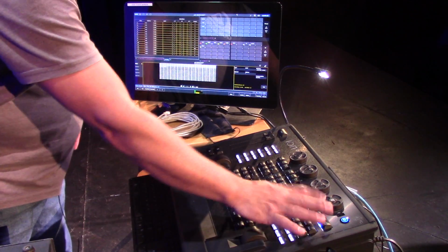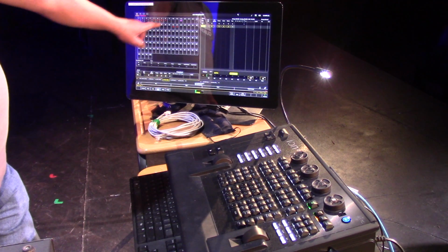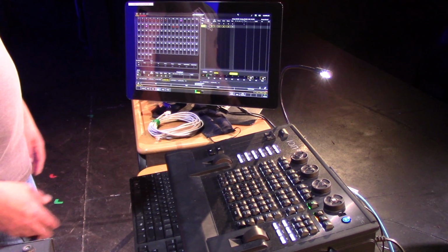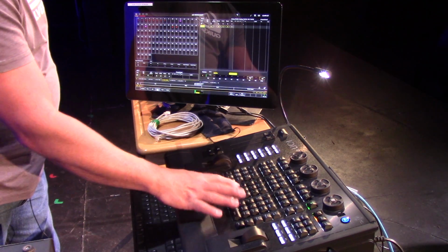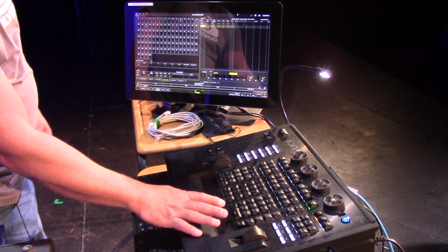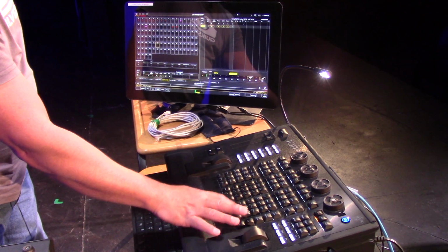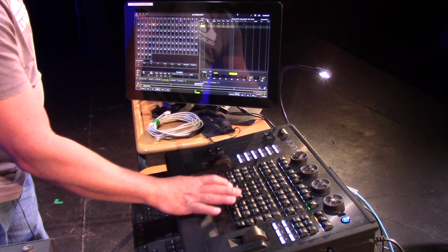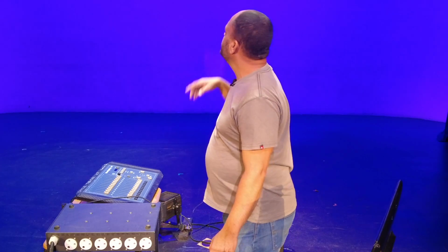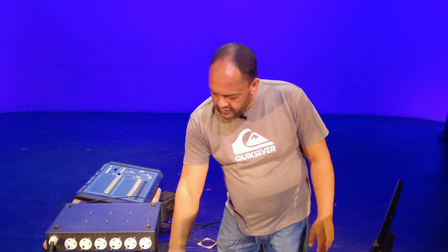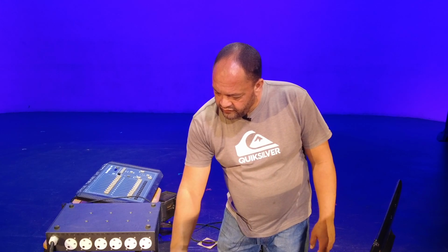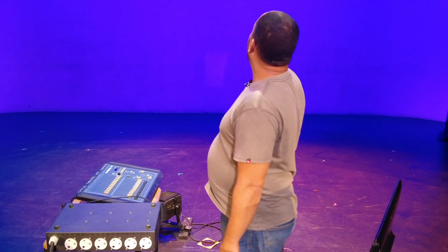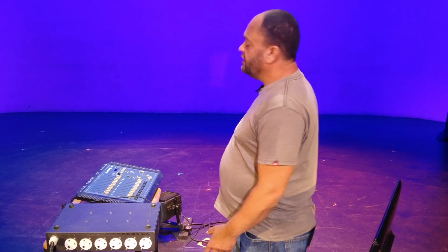So if you then go into live again, that is the channels that we have. So for us to bring up any light, we can always just go channel 70 for argument's sake. You can either go at full, enter. If you go 21 through to 25, at full, enter. That just gives us lights coming up on this bar in any case, or if you go 30 through to 40, that gives us more light on that bar.